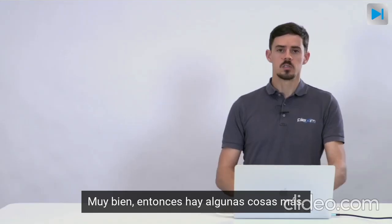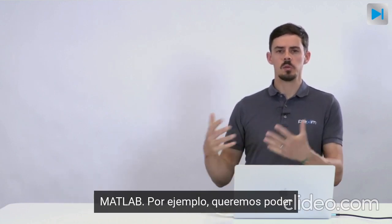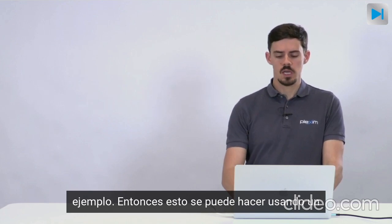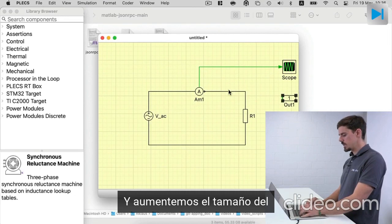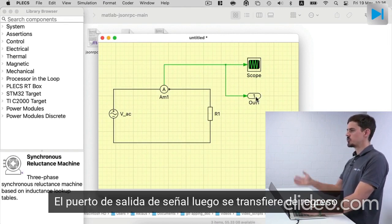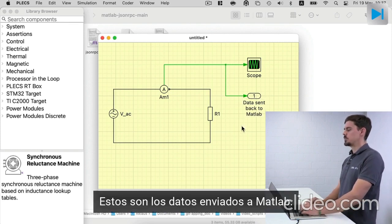All right. So there are a few more things we should do when we want to interface to MATLAB. For example, we want to be able to send back data to MATLAB and to post-process it there. So this can be done using a signal out port. And let's increase the size of the circuit a little bit. And so all the data that enters the signal out port is then transferred back to MATLAB. So this is the data sent back to MATLAB.